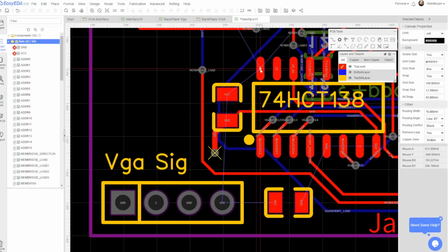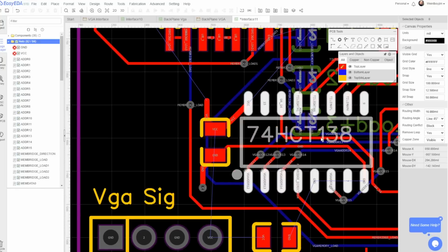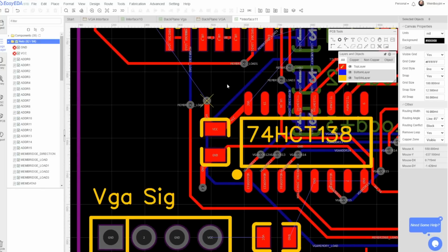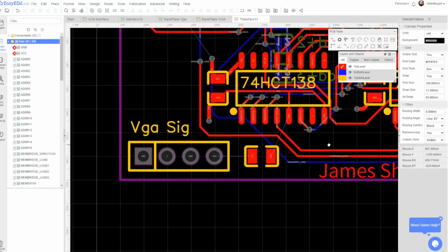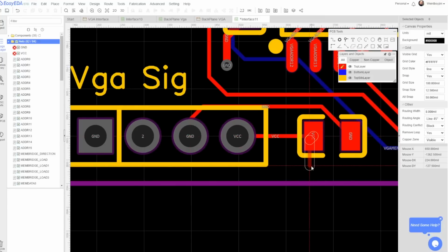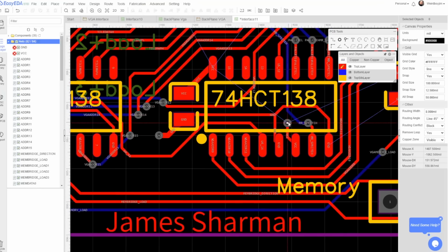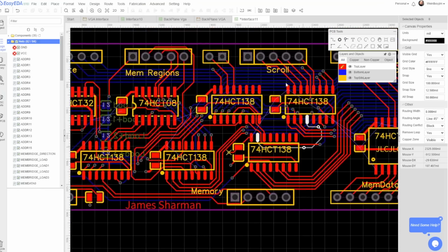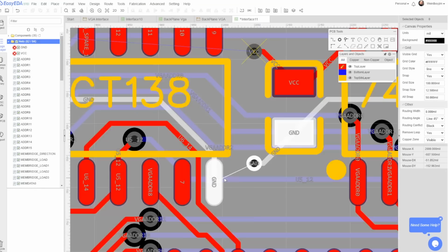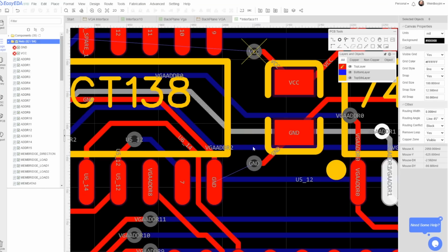Advice I'm being given in the comments is that I should explicitly wire power and ground to the decoupling cap and then go on to everything else on the chip. Separating those is almost irrelevant because the ground fill is going to come in.